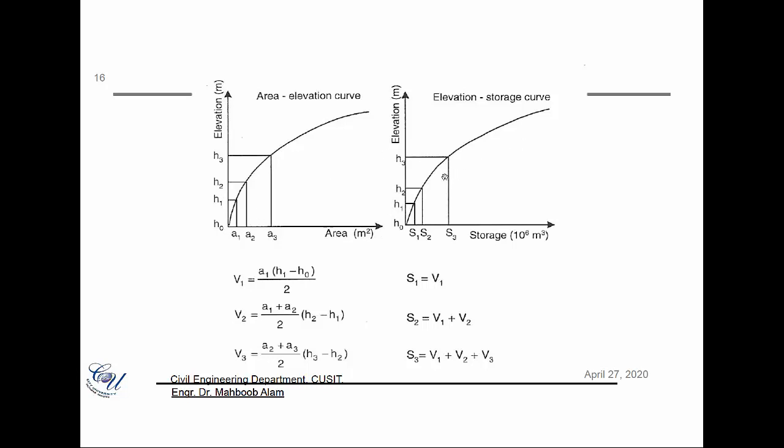Similarly, another relationship which is also associated with the elevation is the elevation storage curve, or elevation storage relationship of a particular reservoir. And here we associate the height or depth of water with the storage that is there in that reservoir. So area is obviously in square meters, storage would be then in cubic meters, and then we can have a relationship between them.